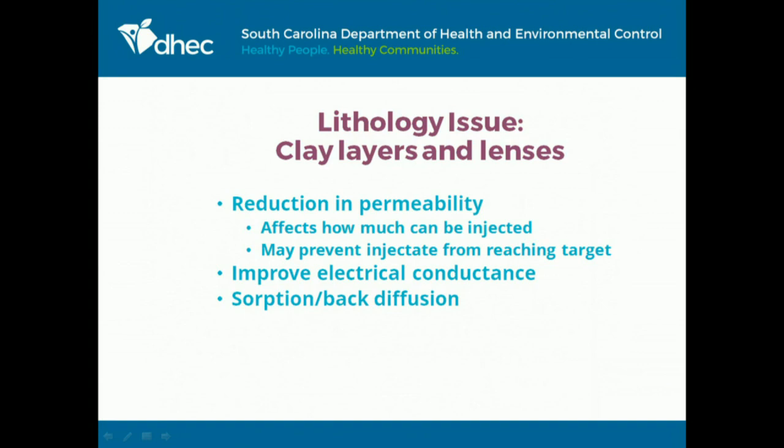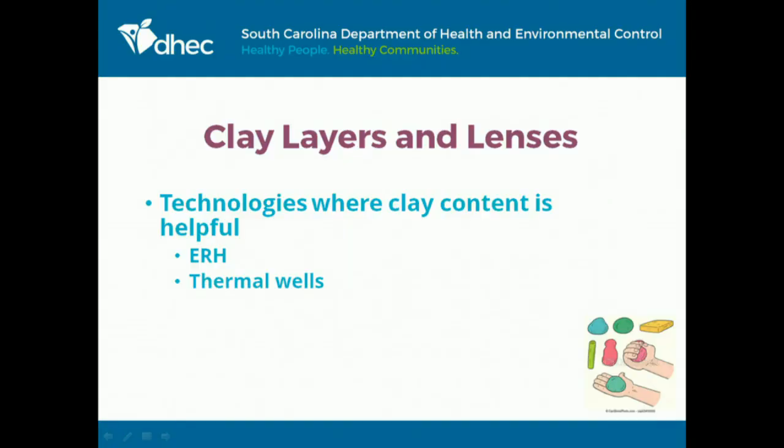Sorption and back diffusion. So clay typically will absorb chlorinated solvents. It likes them, they like each other, and it will hold on to them until the groundwater starts going down in concentration, and then the clay will start to release contamination into the aquifer, which makes it very difficult to achieve your remedial goals. There are, as I mentioned, some technologies where clay is actually helpful. If you're doing a thermal technology like resistance heating or thermal wells, the clay does really well in conducting heat and conducting an electrical current.